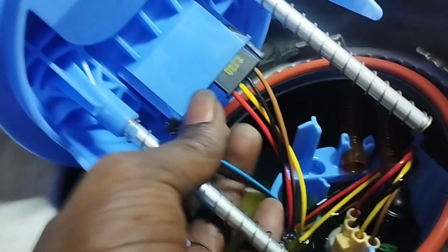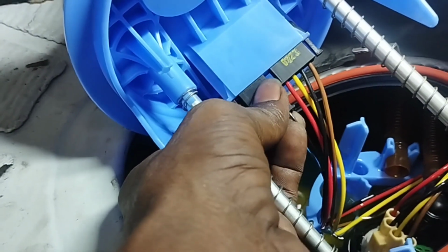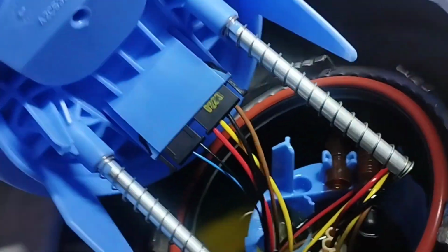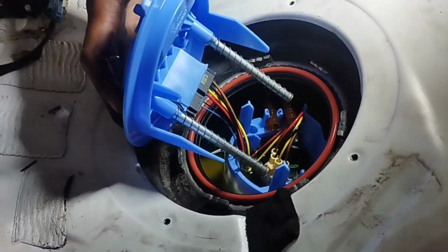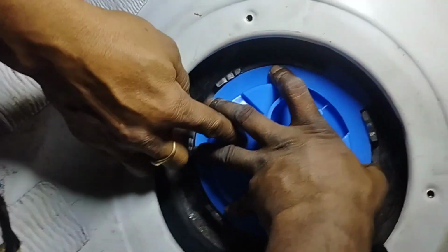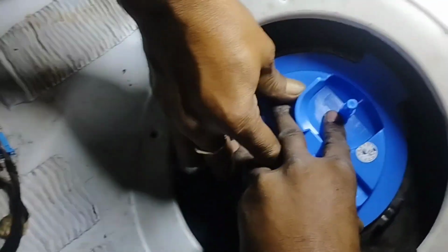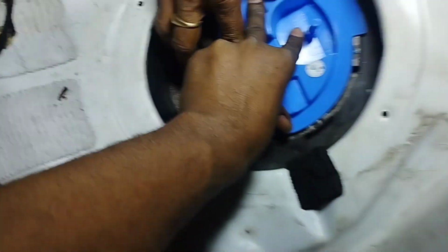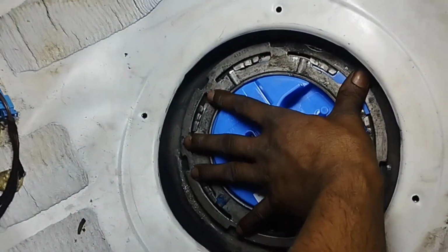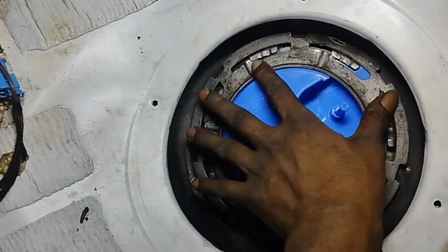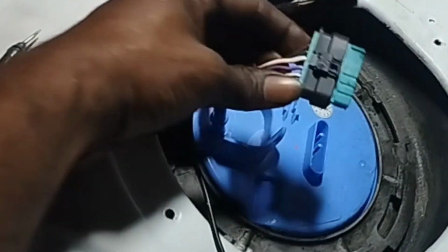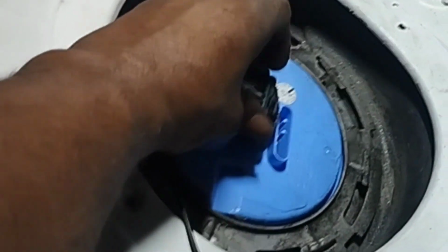Install the upper part of the fuel pump. Connect the 2 wire sockets to the upper part of the fuel pump well. Fit the upper part of the fuel pump well and take care that there is no problem with the bottom O-ring, because if the O-ring is not right, it will leak the fuel and create dirt inside the car. Hold the fuel pump downwards and attach the upper lock bracket. When installing, the lock bracket should be turned to the right. Lock the lock bracket as it was when the lock was opened.